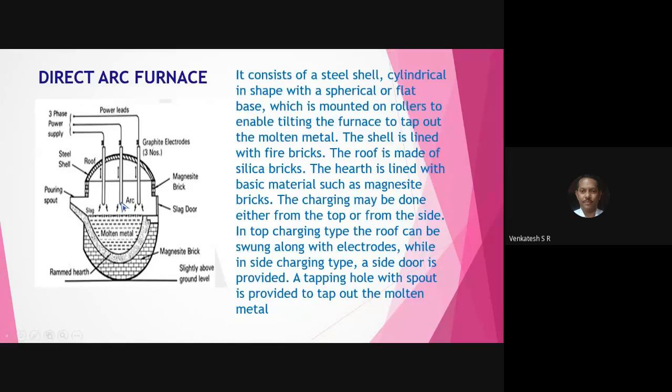The arc has a temperature of 3000 to 4000 degrees centigrade, which is enough to melt the metal present in the furnace. After 2 or 3 hours, the complete iron ore and the alloying elements are melted together, which forms the liquid steel.